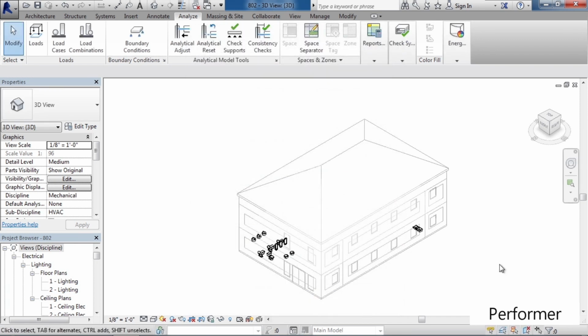So as a review in this lesson, we looked at the energy analysis energy settings. We first talked about the requirement of having a login to Autodesk 360 in order for the analysis to run, because those compute in the cloud now. Secondly, we talked about where the energy analysis settings are located on the Analysis tab in the Energy dropdown section. And lastly, we went through the variety of different energy analysis settings on the Energy Analysis window, including export settings as well.